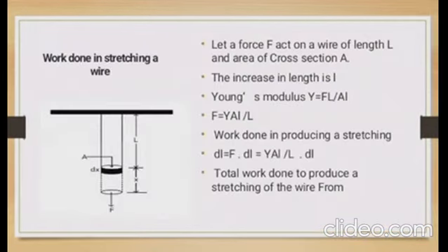Work done in stretching a wire. Let a force F act on a wire of length L and the area of cross section A. The increase in length is l. Young's modulus Y equals F L by A l. F equals Y A l by L.